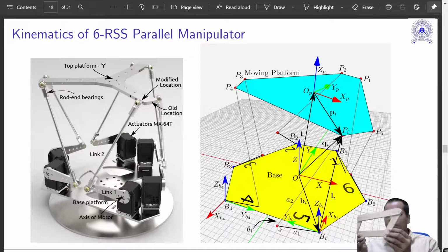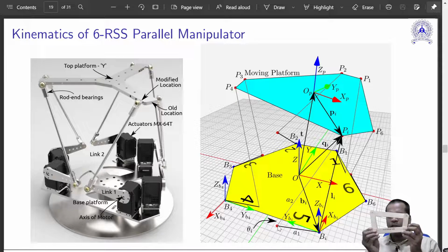Just like the case of this one, what happens? Yeah, this is a 4-bar mechanism. So how many degrees of freedom is this? This is just 1 degree of freedom. So if you lock just one of them, the other one becomes locked even though it is free.